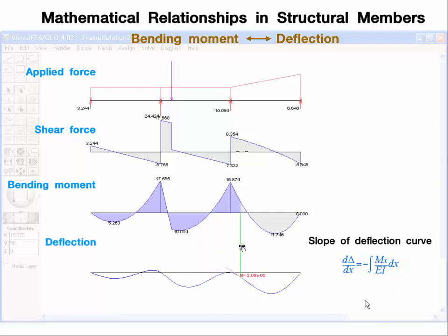If you drag the green line, the slope angle of the deflection curve changes, and the highlighted area is updated instantly, following the green line. You may select a portion of the beam by clicking 2 points on the deflection diagram. The boundary of the selected portion is represented by 2 green lines. The area of the bending moment diagram in the selected part is highlighted in blue color.